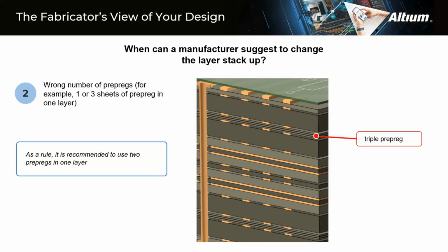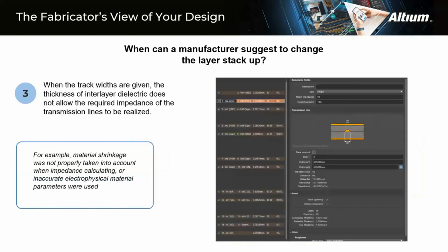Designers want to be sure to study the requirements for the layer stack up and, if possible, use known good layer stacks, either from within your organization or from your printed board fabricator. A manufacturer can offer to change the thickness or types of dielectrics using the layer stack-up.